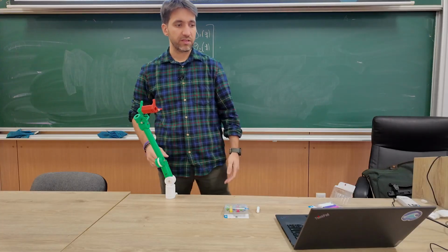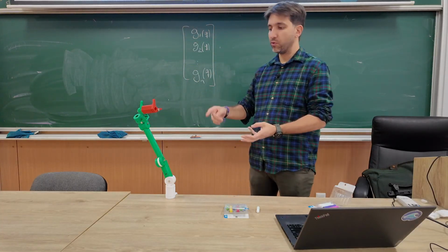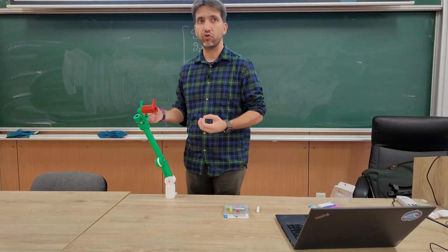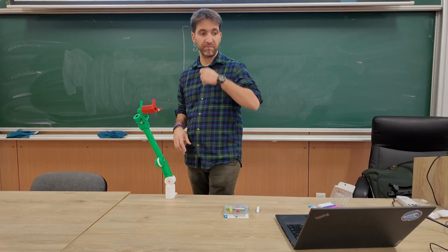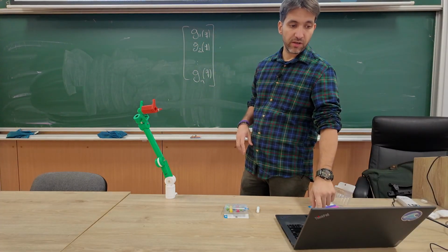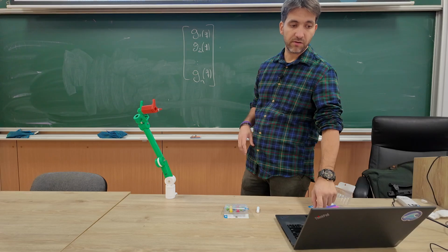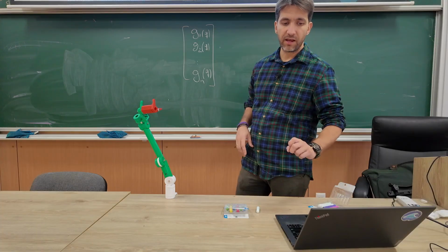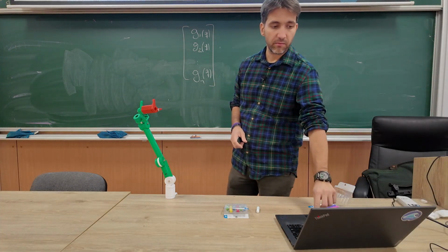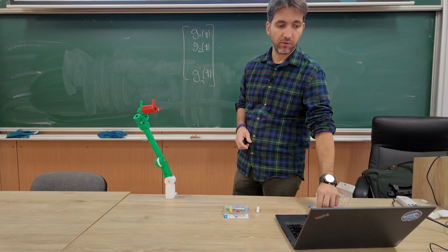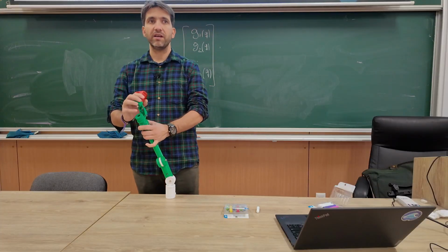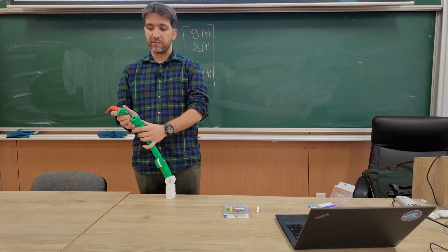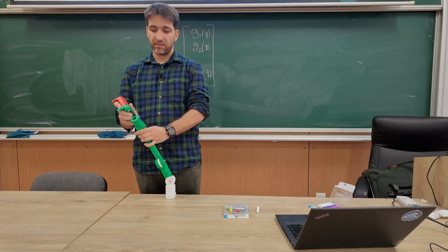Okay, so that's like one example. The position of the joints affects the torques I need to send to all the joints in order to stabilize the robot, right? It's not just the position, it's also the velocities, right? And that's something you haven't seen in the lab, but you will see this week, how this term affects basically the behavior of the robot. So we call this the Coriolis or centrifugal terms. So this has to do with basically how velocity affects the torques generated at some joints.